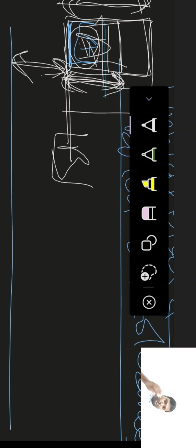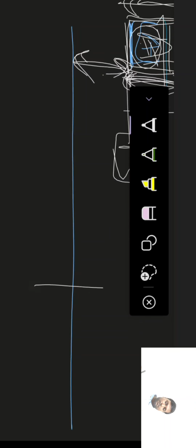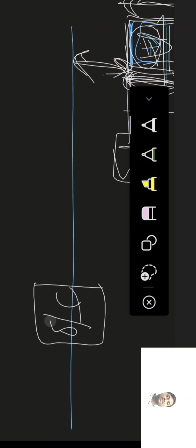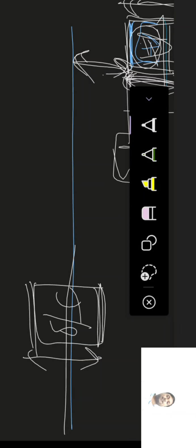There are some fundamental deviations like JS. JS is represented something like this. It means one limit is above the zero line and the other limit is below the zero line. That means the tolerance zone will cross the zero line, and such a tolerance will be called a bilateral tolerance because it is on both sides of the zero line.